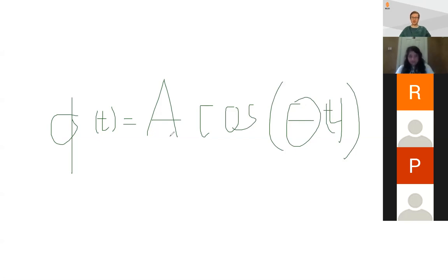Yeah. And then when you do phase modulation and you're taking the derivative of the function, is it at the continuous points or the discontinuous points? For phase modulation, you would take the derivative to find the instantaneous frequency, which is the frequency of this cosine at any given instant.